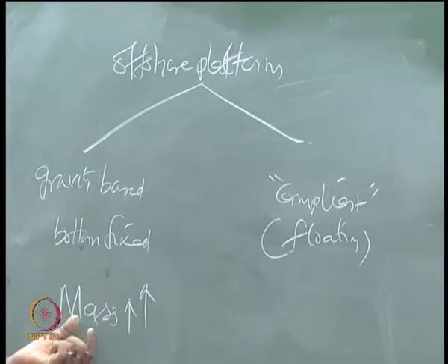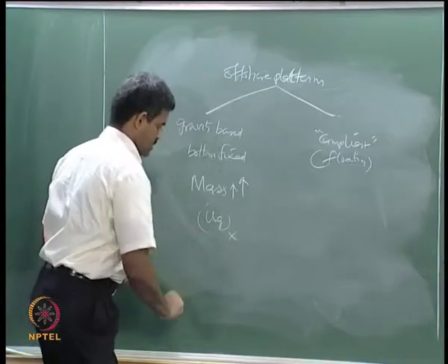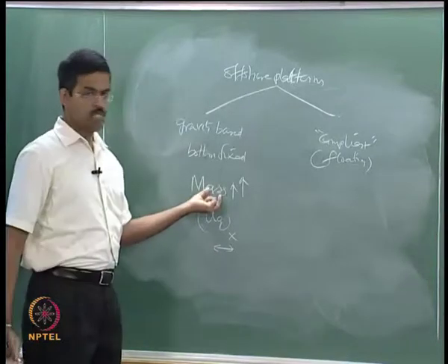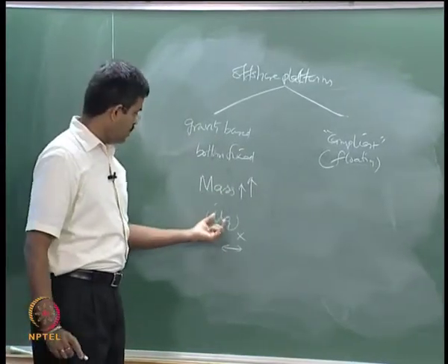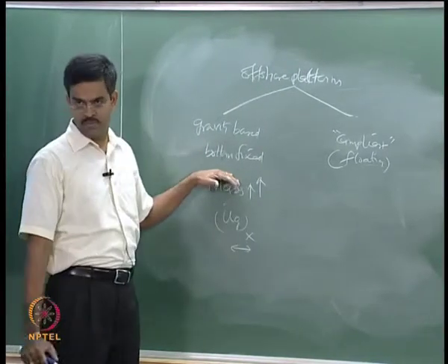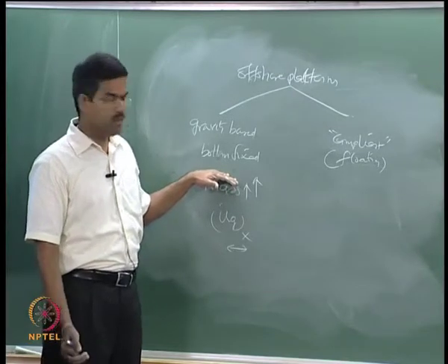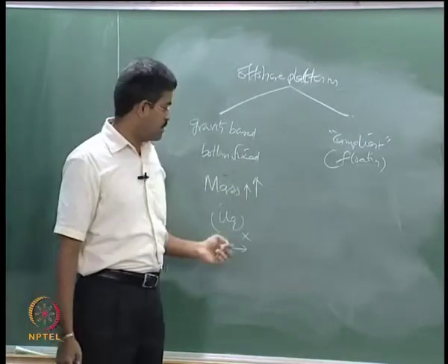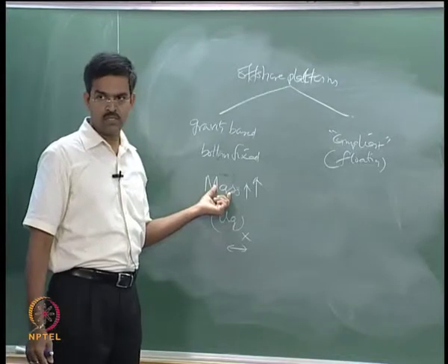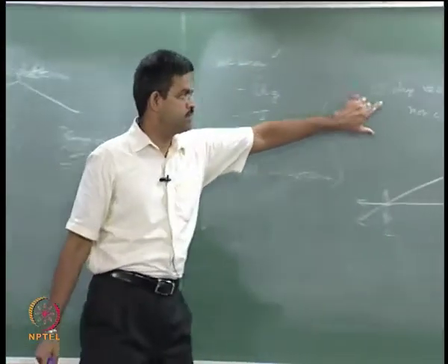When the member is having enormous mass, U double dot G in the x axis will cause inertia force on the system, while U double dot G in the z axis will be counteracted by the mass. Okay. So, the member will have an indirect effect, but the mass is very large compared to the amplitude of this motion, so it need not be considered.